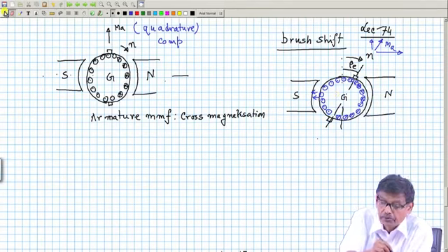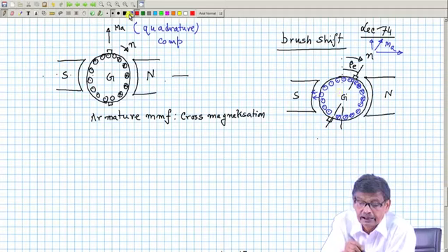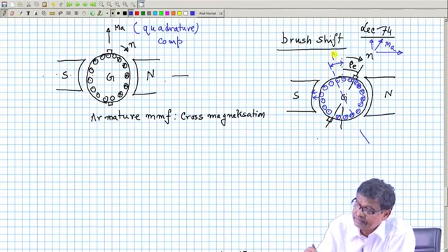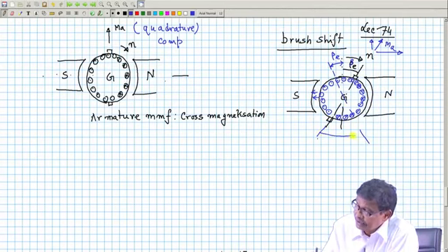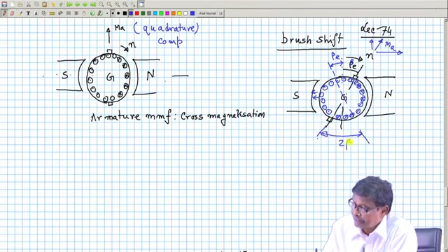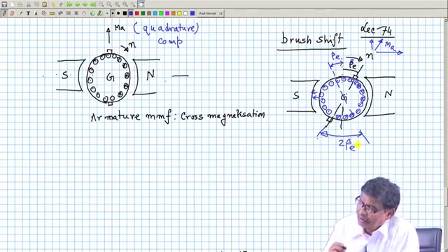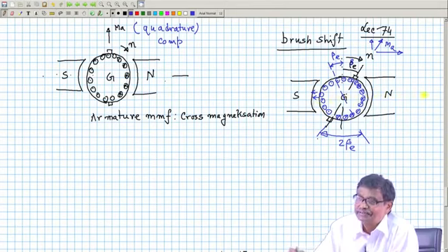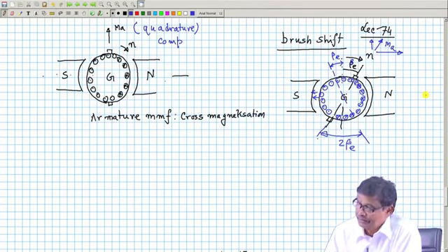What you do is draw another line here, such that you imagine this line also at beta E, same as the electrical beta here, so that this angle becomes 2 beta E. People then say that the conductors in this 2 beta E and in this 2 beta E will give you the direct axis ampere turns produced by the armature.